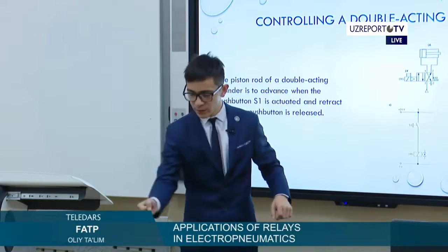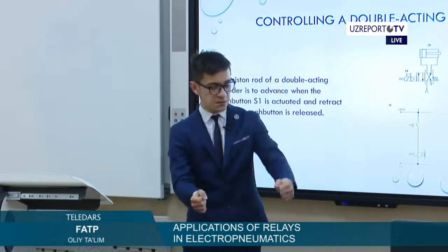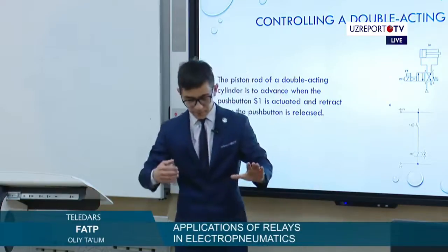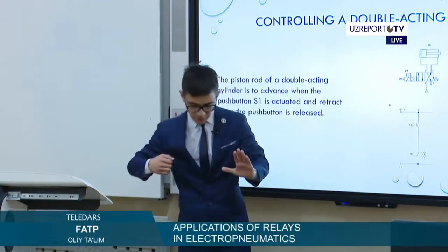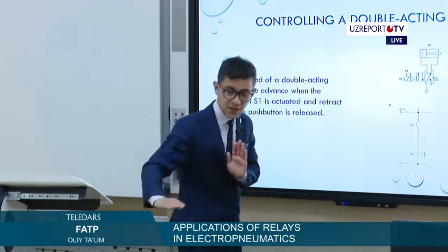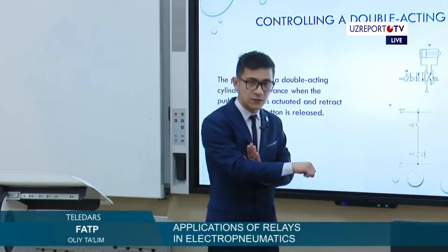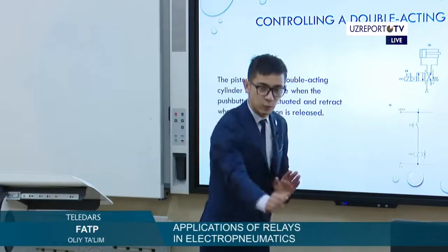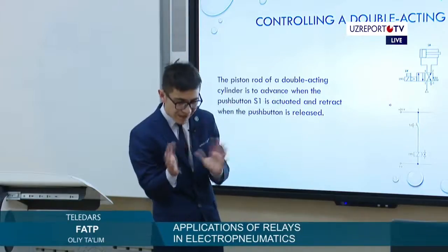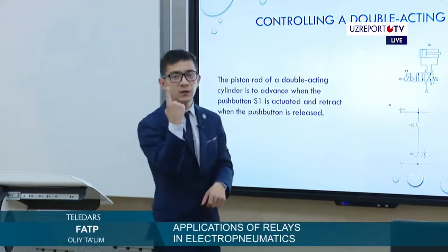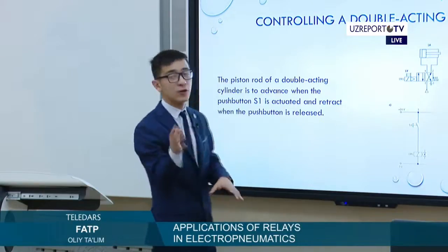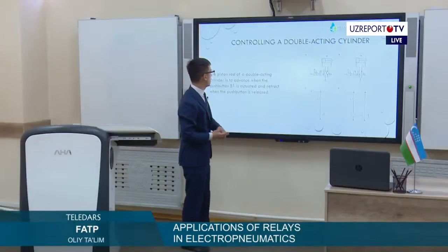One of them is a moving line. The next one is stamping, a mark, say. When the piston works, in the first place, the piston will come to the first section and your line starts to move. When it comes to the second place, it makes a stamp on the product which you put. So you can make two different actions in one machine, a pressure machine, according to the work of the cylinder.